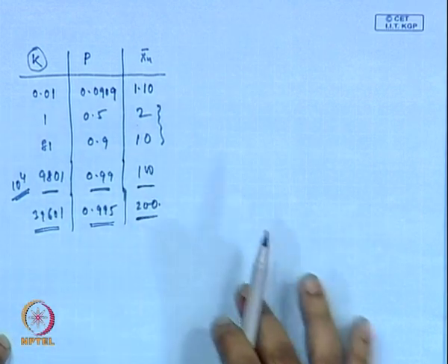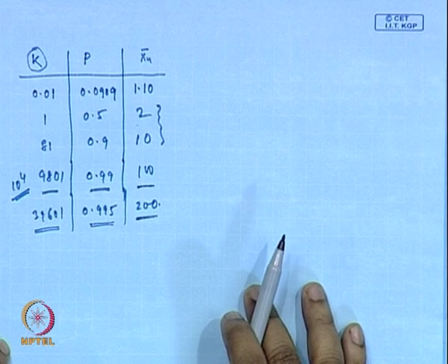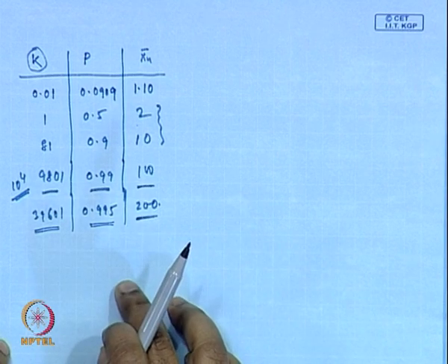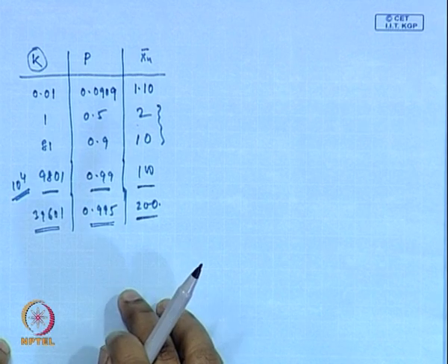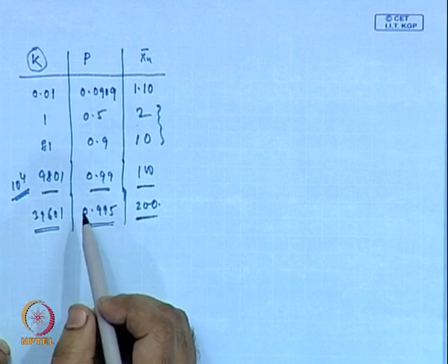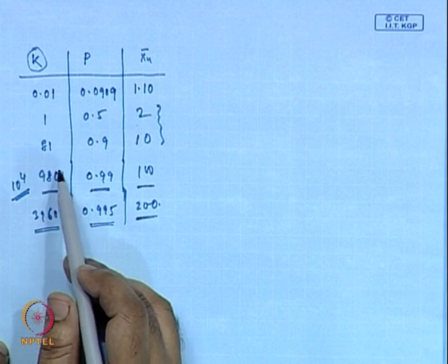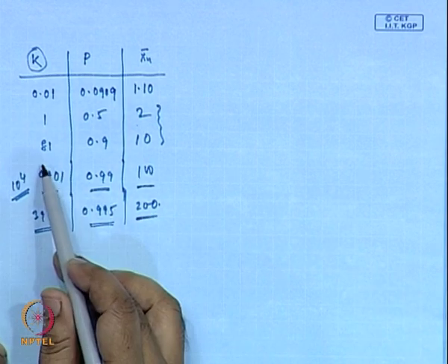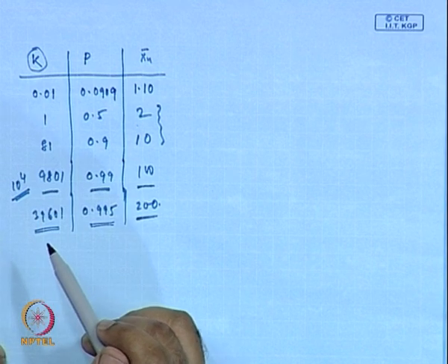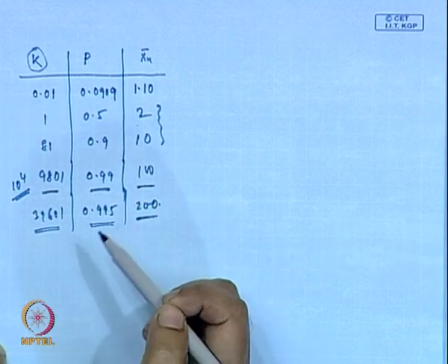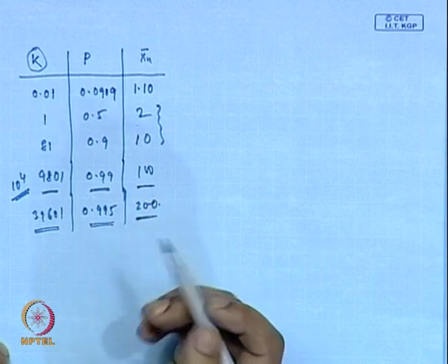So, that gives the importance of the equilibrium constant in a step polymerization reaction. You are always better off having a reaction with a high equilibrium constant. So, this convinces us that there is no other way, we have to do a reaction where we continuously take out the condensate from the system.